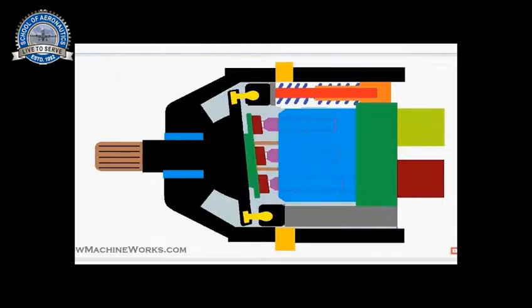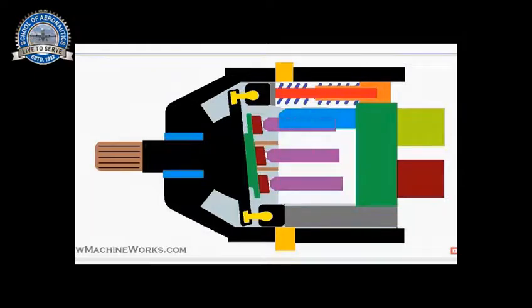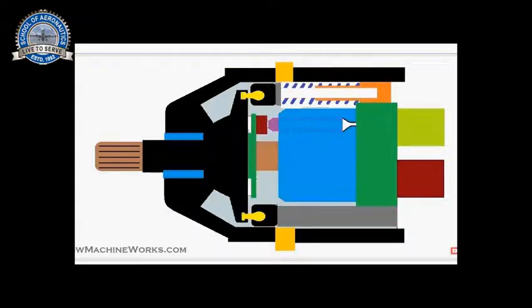So we have more number of pistons arranged. So you can see when more number of pistons are getting arranged, the top pistons are moving towards the back as per the swash plate angle, and the bottom pistons move towards the front due to the same angle. So I am releasing the pressure. As a result of this, the swash plate becomes vertical.